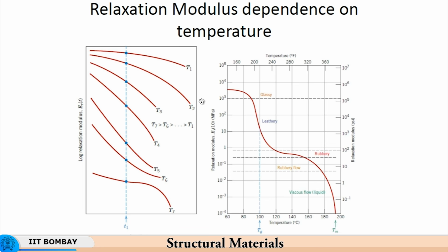In the rubbery state, you have partly the characteristics of the solid state below the glass transition temperature, and partly the viscous state of the liquid which occurs above the rubbery state. If you go on heating it and cross this rubbery state also, then you will have viscous flow of the polymer. It will tend to melt.